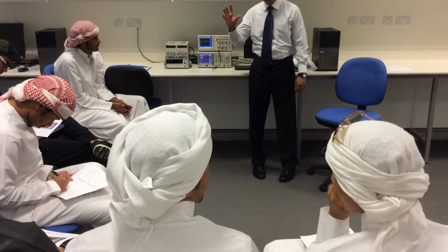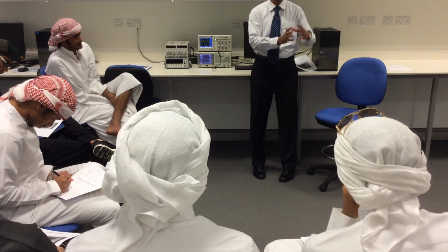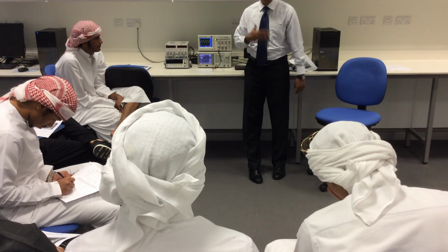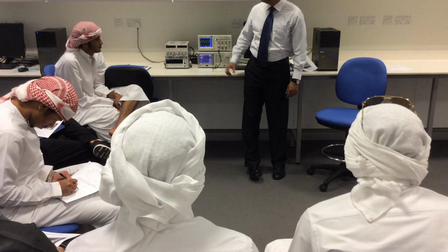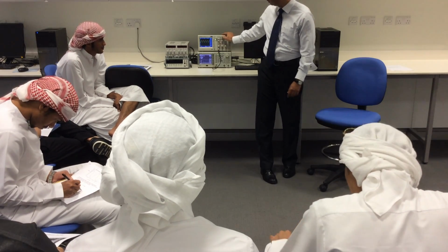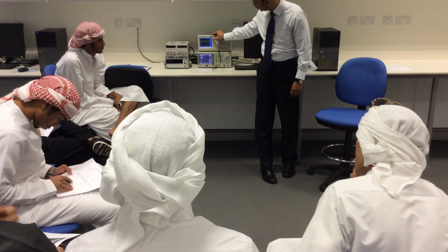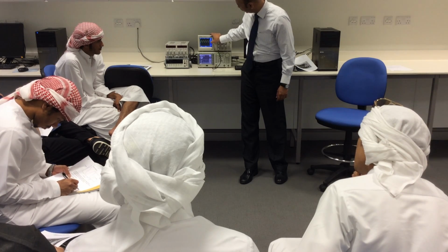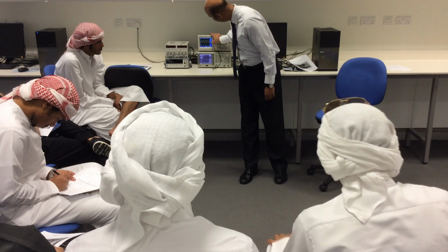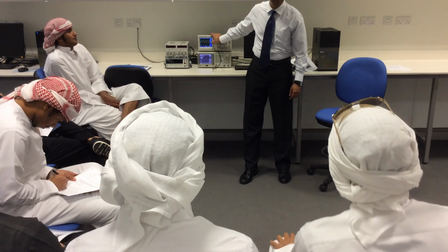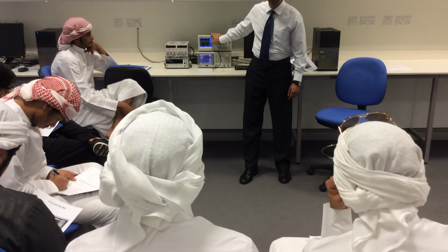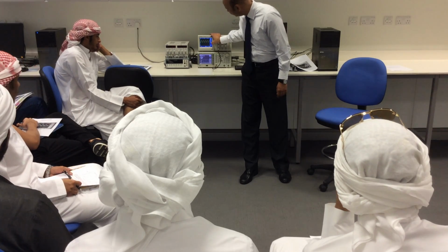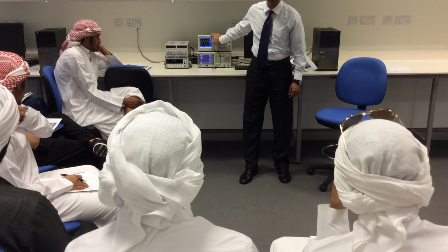Now, these are the visual inspections. You can quickly look at the blocks, count the blocks on the voltage axis and on the time axis, and get some sense of the values. But you see this measure button? You click this measure button and you will see this value and channel 1. And here you select the type. So for example, frequency. It shows you frequency, 100.4 hertz. So now it is measuring the frequency for you. The measured value fluctuates, but it is 99.9, 100.2, something like this. Okay.